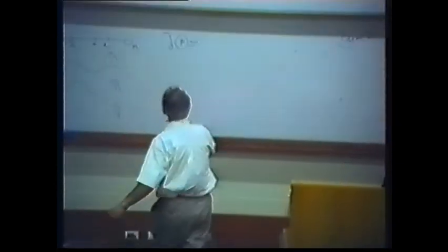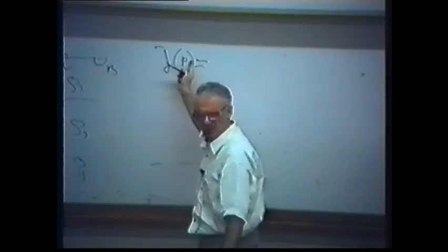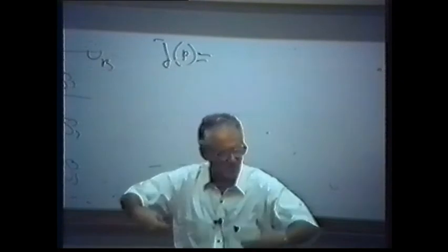So when I write this vector, we will use it in electromagnetic fields everywhere. That's the reason why I'm preparing you. Current density, it's not simply vector J. My suggestion, visualize the amount of charges. See it. You tell yourself, aha, J equals such and such amperes per meter squared. If it's equal to 10, it means 10 coulombs cross per unit time, 1 second, per unit area, and the area is perpendicular.